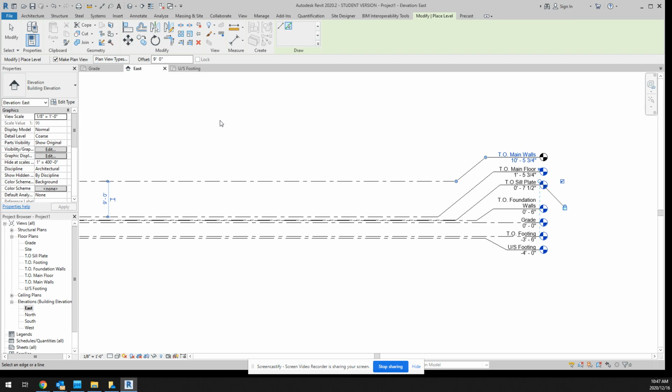So to do it properly, the minimum amount of levels is actually 7 levels. I told you guys earlier that it was going to be 6, but 7 levels is what we should set up. And now you're ready to move on. After you do this, you're ready to move on to the next step, which will be creating our custom wall types. So I'm going to stop doing lessons now. I'm going to allow you guys to create your levels for your cottage.